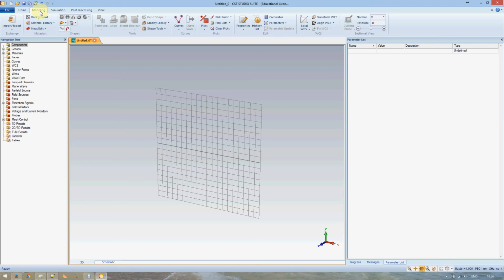CST can simulate all sorts of weird and wonderful models, but if you can't actually build them, then your simulations will be for nothing. You'll be wasting your time. So this is something to bear in mind. Find out if you're planning on building any of these things, where you would manufacture them, what the process requirements are, what the limitations are, and do that.